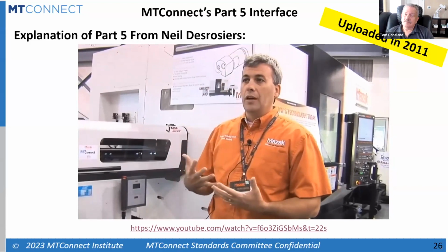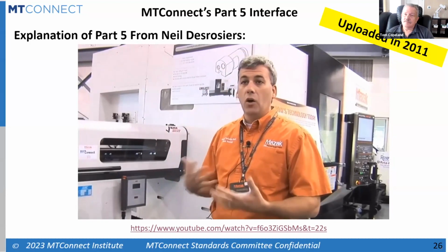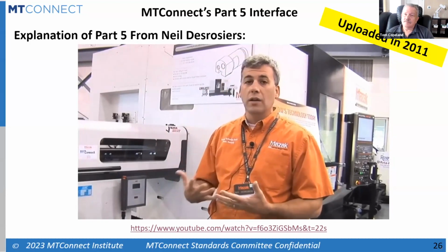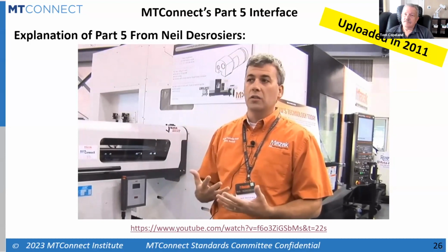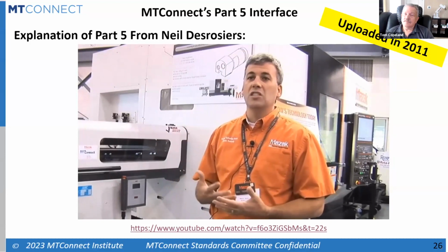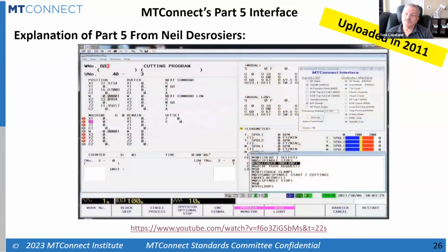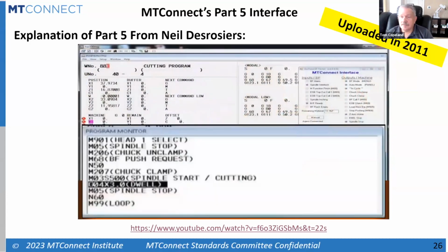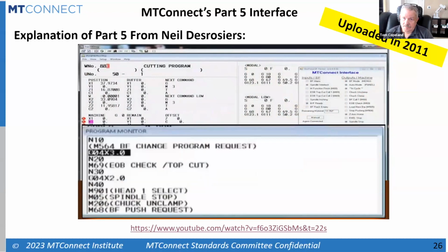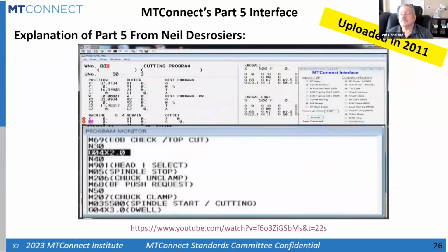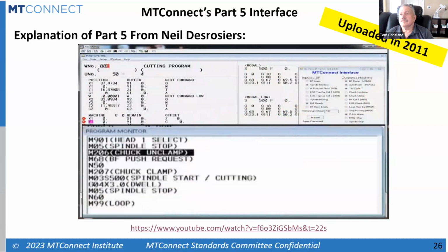So traditionally, a bar feeder in a machine has a digital I/O interface, where it's a series of wires and yes/no signals, on and off signals, and its intelligence is limited. With MTConnect, we're using Ethernet as its protocol. What we've done is eliminated a whole bunch of hardware and wiring, and also enhanced the vocabulary and the capabilities of the communications between the two devices.